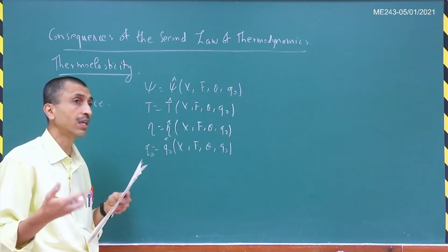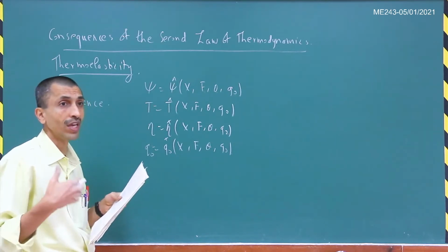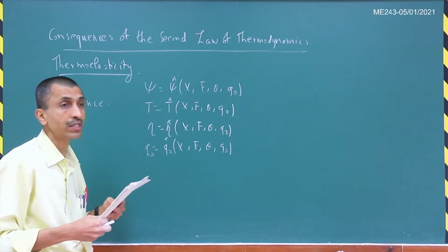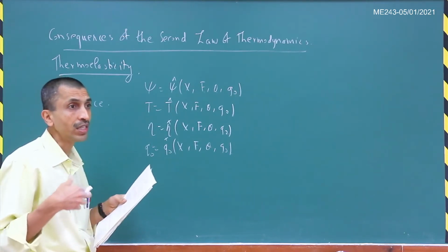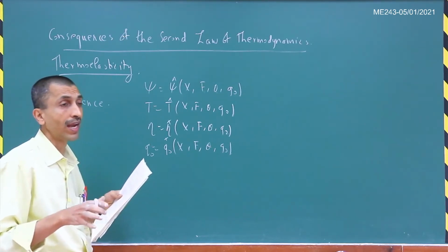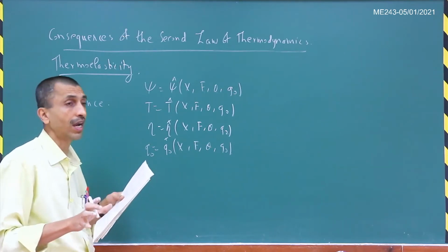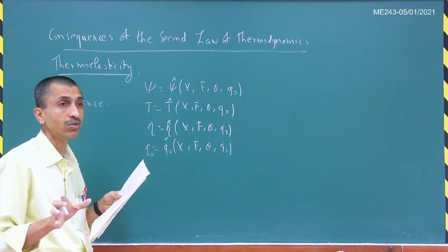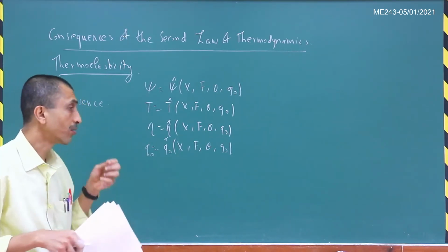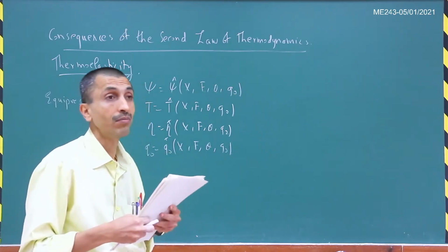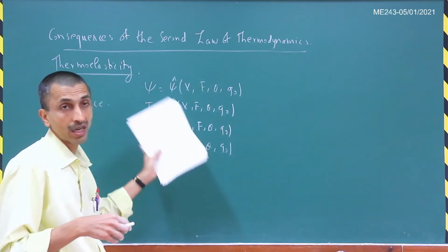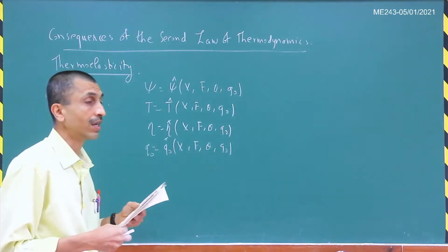Basically, the history of some of the variables will also play a role. For example, in the case of non-Newtonian fluids, a significant part of the history of the deformation gradient will also play a role in influencing the stress. And exactly how much history to take, or what kind of functional to take, are very difficult issues to resolve. So basically quantitative modeling is one of the biggest challenges, and as I said, unless you get this kinematical list correct, there is no hope of reaching the correct conclusions here.